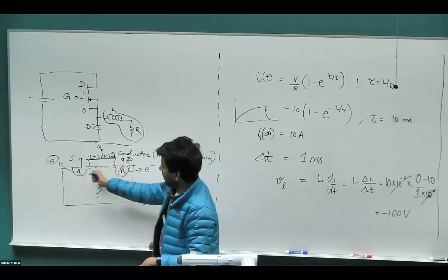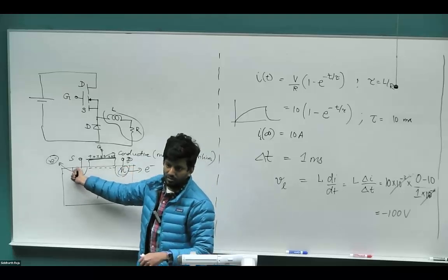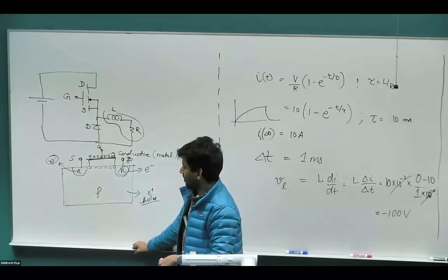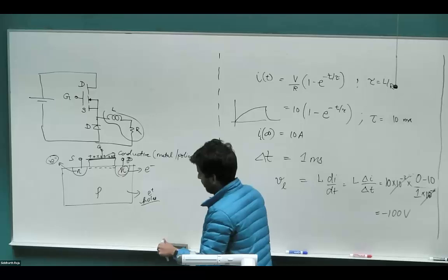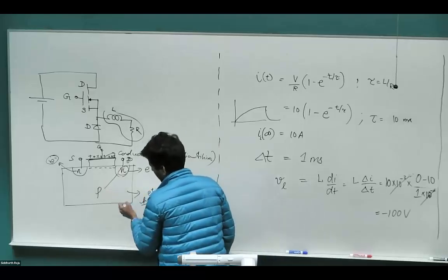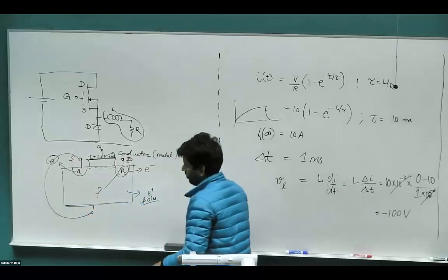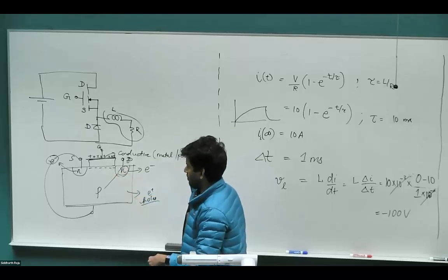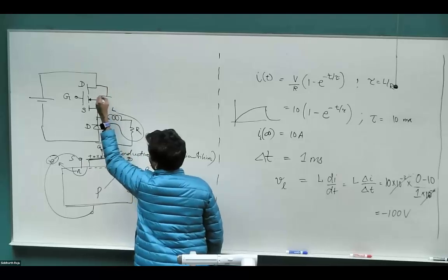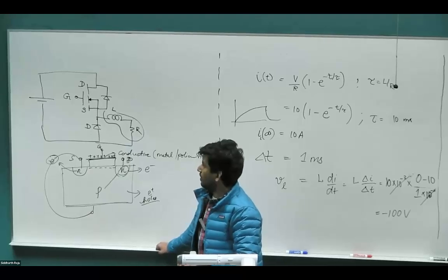And the thing is, a MOSFET can conduct in either direction. So you can pass current from the source to drain or from the drain to source. Right? It's a bidirectional conduction device. Which is not the same with IGBTs and so on, without a body diode. So the way the body diode comes into the picture is because of this channel that we have here. Typically the substrate is shorted to the source during the device manufacturing stage. And this PN junction forms the body diode that's always there in the MOSFET. So a MOSFET, whether you like it or not, always comes with a body diode. If you don't want that body diode, you can get specialized IGBTs that don't have that.